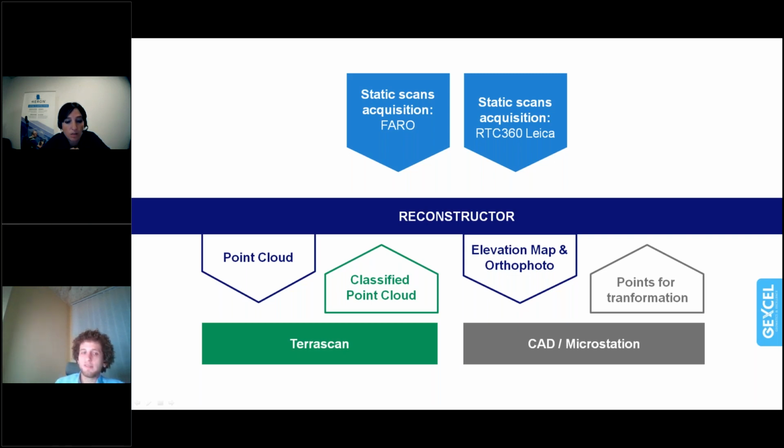The concrete example that I'm bringing you today is also a logistics center situated around Budapest. It was a total of 45,000 square meters. The actual example is going to be a department of this, 6,500 square meters, which can be surveyed with a laser scanner during the day, also taking care of the proper positioning and geometric control with the classic geodetic tools.